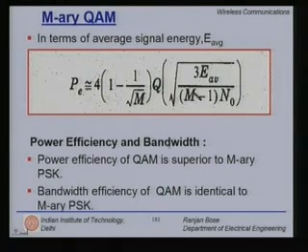In fact, the moment you start going for higher modulation schemes, then you switch to QAM. It's not wise to go beyond 16 PSK, and you rarely hear about 32 PSK because you have to be on the circle, whereas 32 QAM, 64 QAM, 128 QAMs are well known.